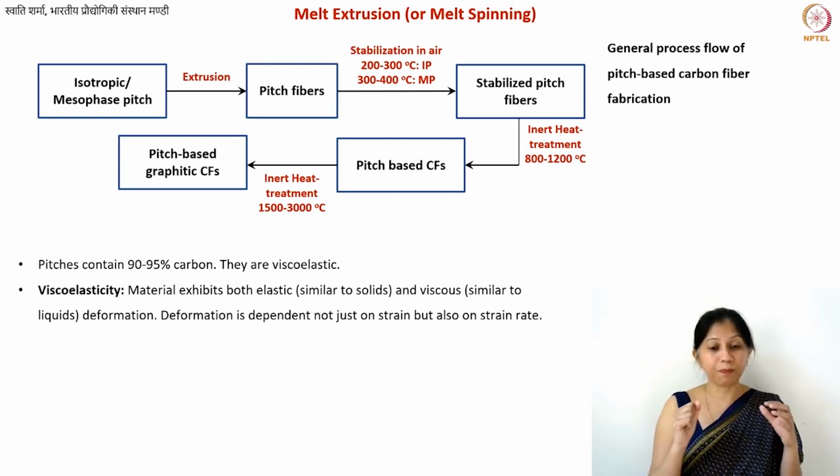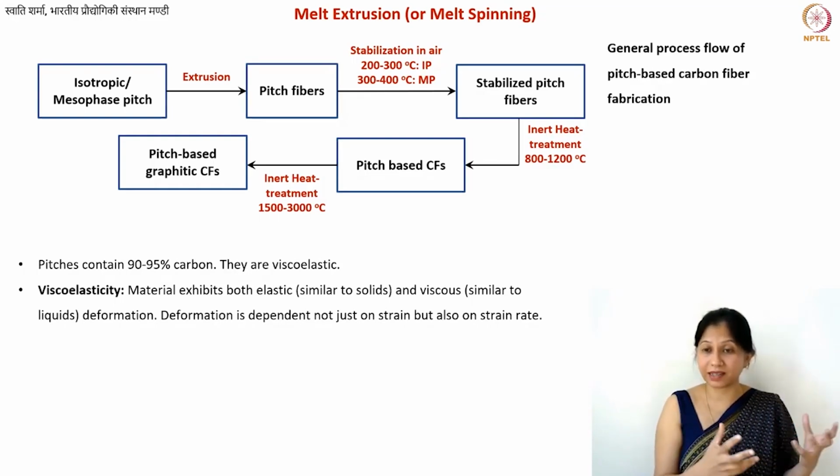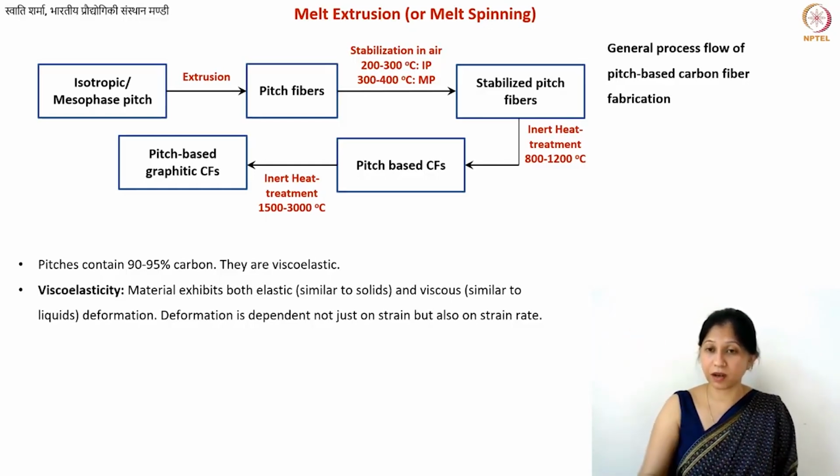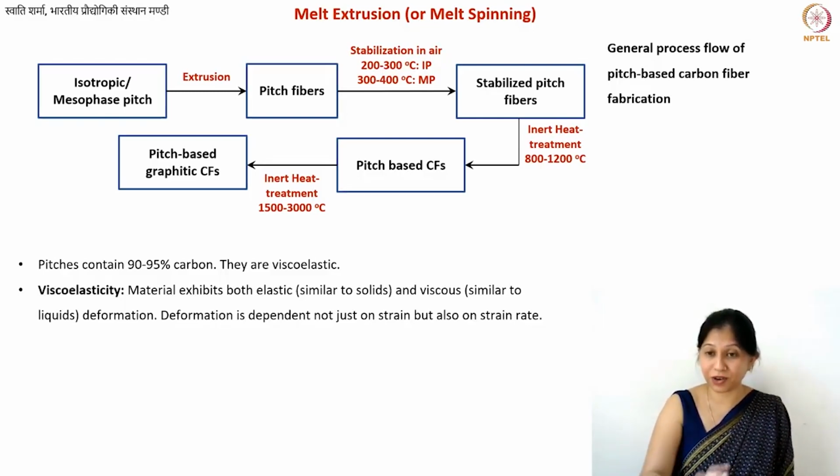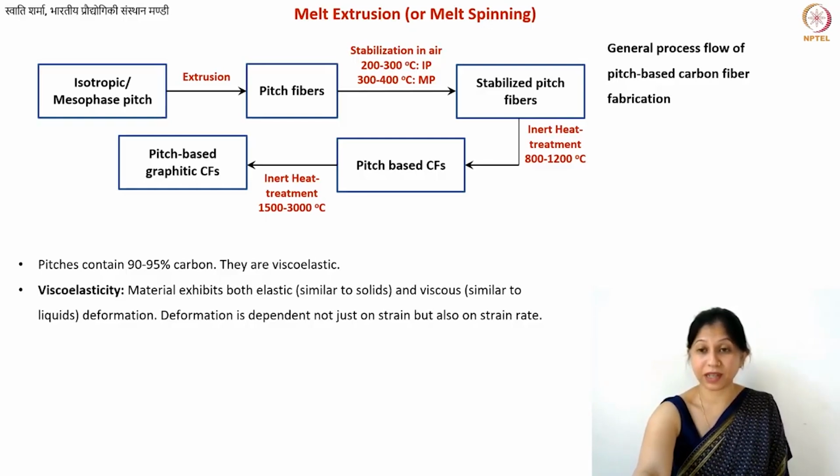Because if it is just a liquid, not elastic at all, if it has only viscosity, let's take an example of water. Difficult to pull water fibers, right? So we definitely need elasticity. But since it is a liquid, we also need some viscosity. So we do need some liquid-like properties, because if it's a solid material, just a crystalline material, then also it's not possible to pull fibers out of it. So viscoelasticity is a very interesting property that pitches have, and that a lot of polymers also have.